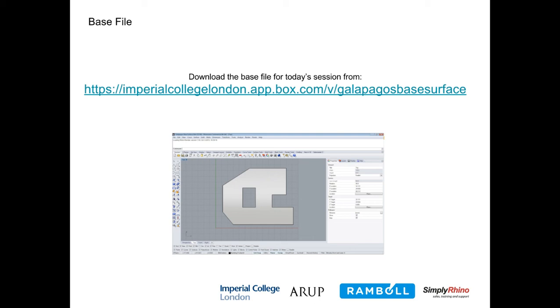And what we're going to do with this is we're going to take that surface. We're going to use Grasshopper to set up a plan arrangement of columns following a regular grid. And then once we've got that working, once we've used Grasshopper to create all our column positions and set that out, we'll then be using Galapagos to try and optimize that arrangement and try and come up with an optimum column arrangement for this particular building footprint.